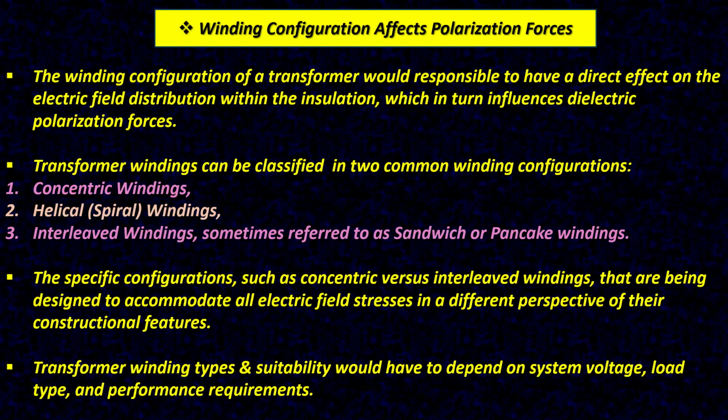Transformer windings can be classified in three common winding configurations. One, concentric windings. Two, helical or spiral windings. Three, interleaved windings, sometimes referred to as sandwich or pancake windings.